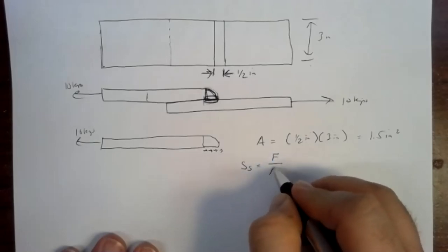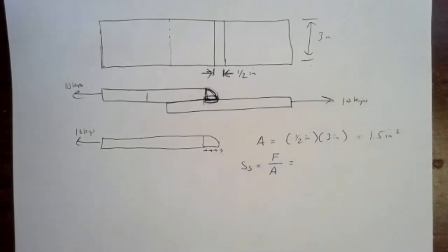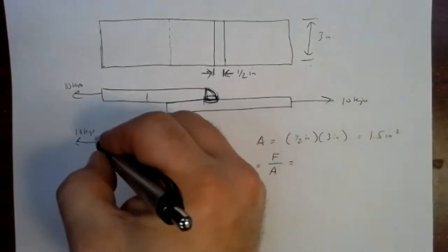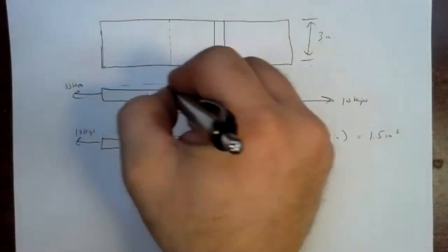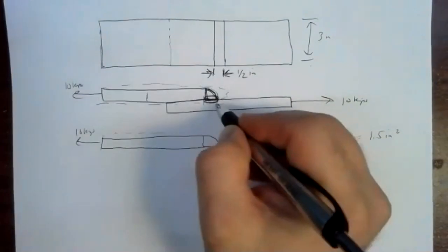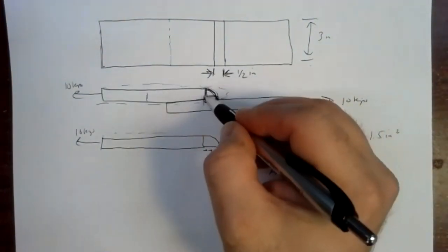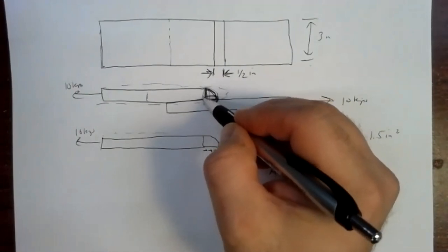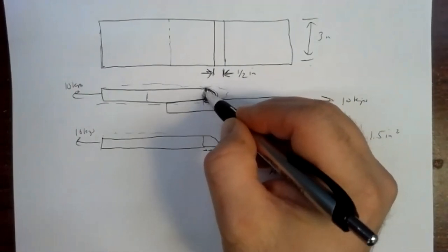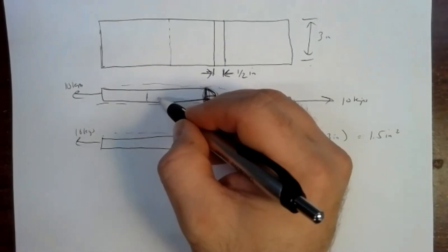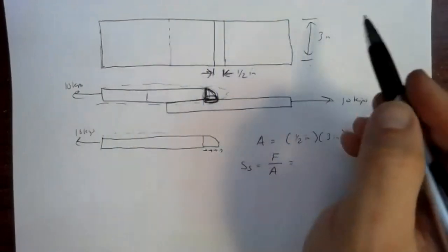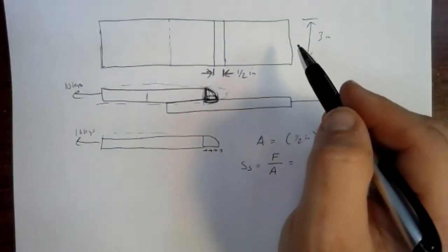Sorry. So we disregard the part of the weld that's on the upper portion of the material then? Yeah. We're not worried too much about the tensile stress there, because at least where I've drawn this, how I've drawn the free body diagram, I've cut through the bottom portion. If I wanted to know the tensile stress right here, then I'd have to know something about the thickness of the material and the length of that weld to be able to figure that out.